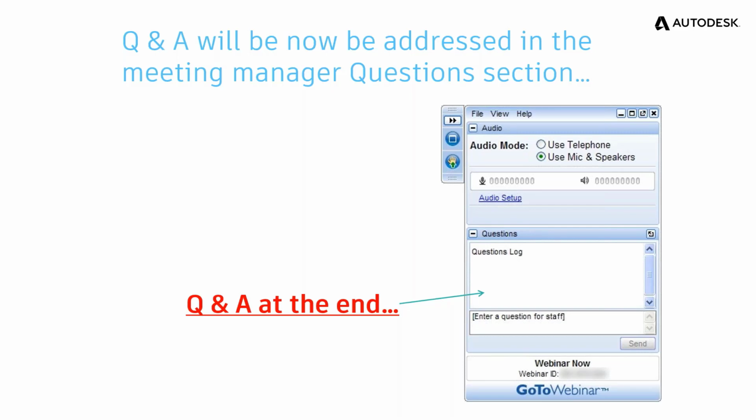It's going to ask you if you want to do that, of course, but it's going to want to overwrite it, which means any of your doors that were already in drawing one, which were standard blocks, would be replaced with the door from drawing two that is a dynamic block, which means now all of your doors you had in place become dynamic blocks. Will they change position? Yeah, if the insert point is different between the two objects, yes.